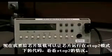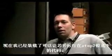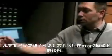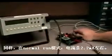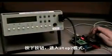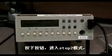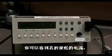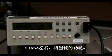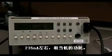Now I'm going to take us into some code that's going to drop us into stop 2. Alright, so now we've got the part loaded with some code that's going to put it into stop 2. Again, we're in a run mode at 2.3 milliamps. I'm going to go ahead and hit my button to put it in stop 2. And as we can see, we're even lower than we were in stop 3. This will settle out at about 235 nanoamps. So pretty good power consumption there.